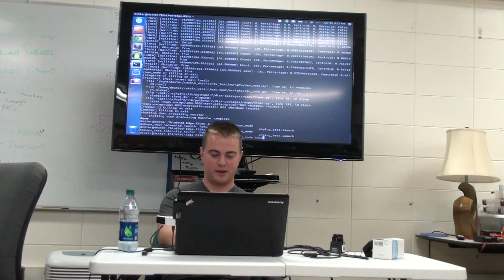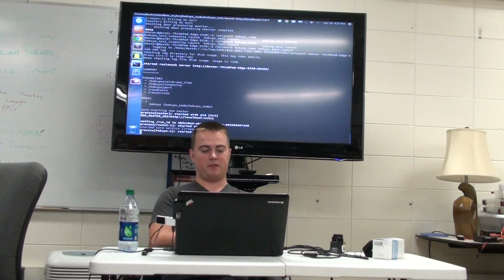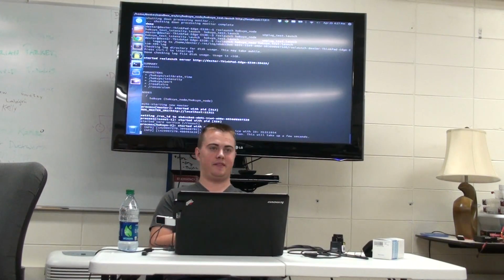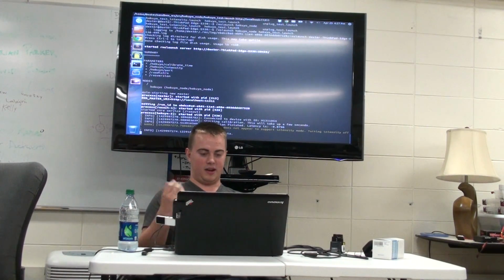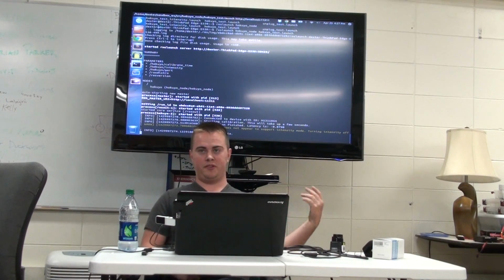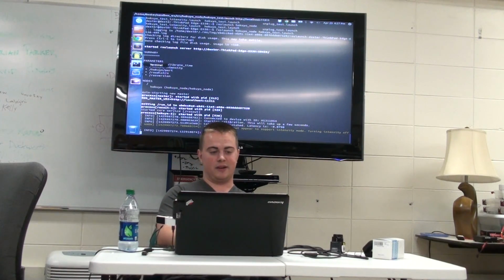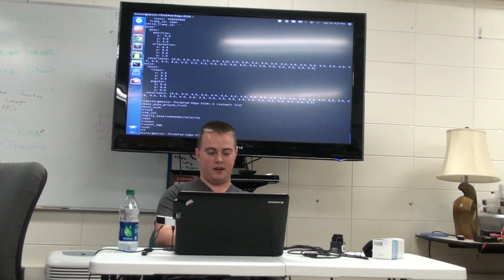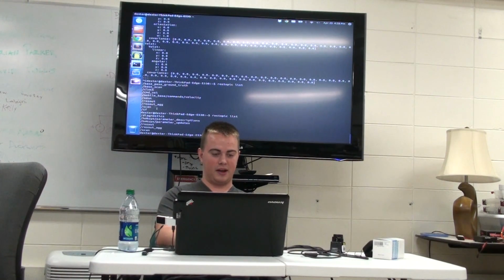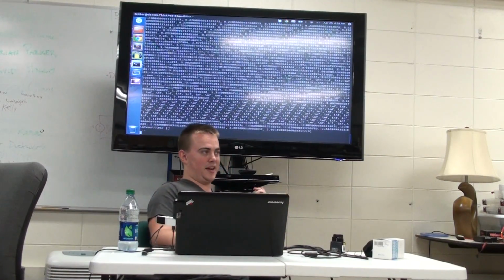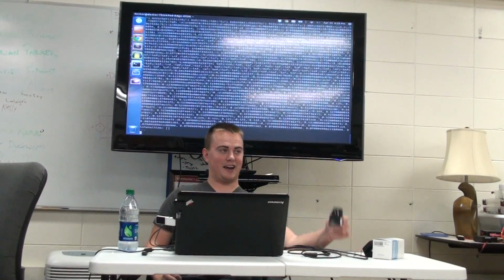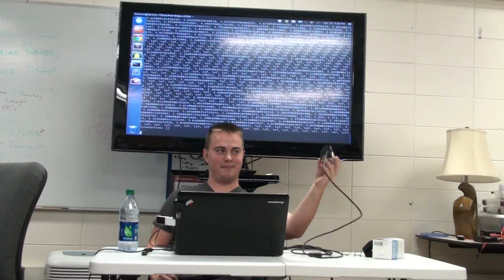Oh, I stole that. That's why. hokuyo_test.launch. Okay. And so I'm going to run that, and again, this is all predefined. I did not make any of this. So it creates the nodes, and now it is streaming laser data. So I can now go over here and list. Now there's a scan topic running. I can again echo scan, and now I see laser data again, but it's different laser data because this is actually from a real sensor, and I can change it by moving it.